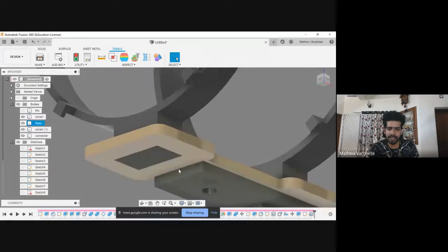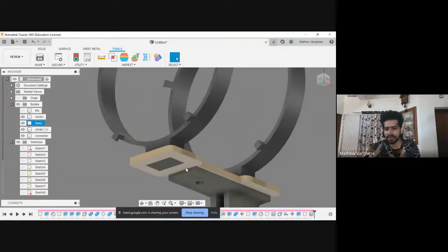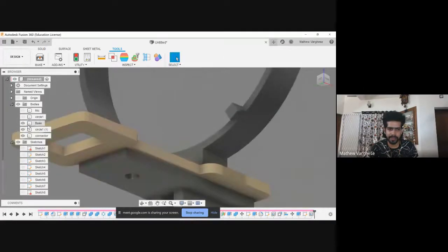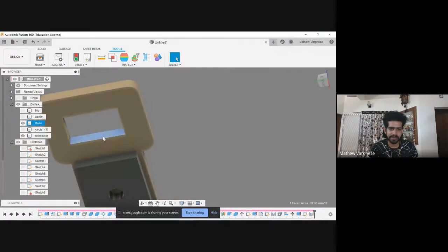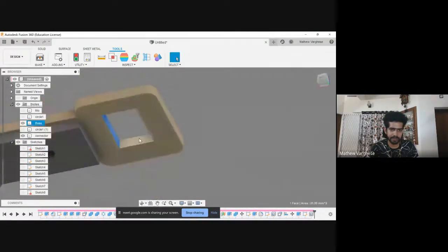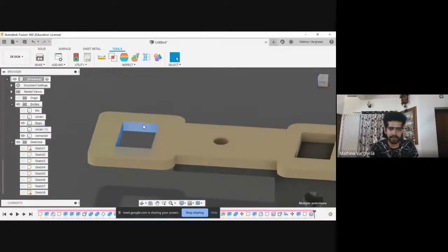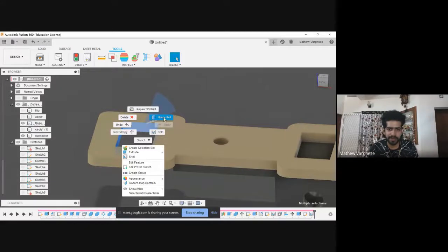We forgot one thing. During 3D printing, the sizes of these holes and all these things change a bit, because this plastic contracts when it is heated and cooled back. So we need to factor that into consideration. For the circles, it is not problematic in our case, but in case of these places, we have that problem, because the holes need to be very good. Like, small tolerance should be there.